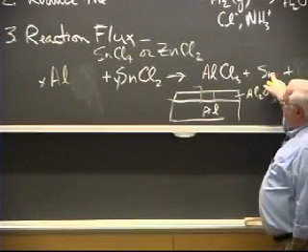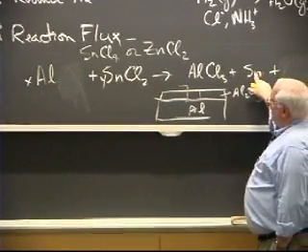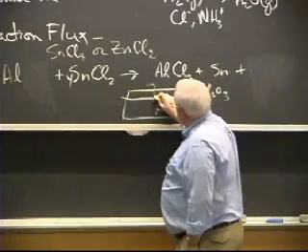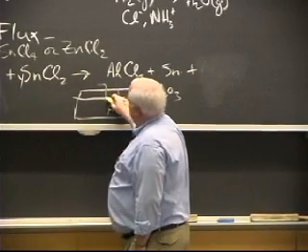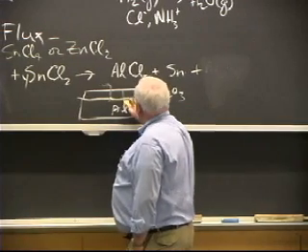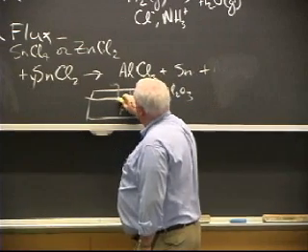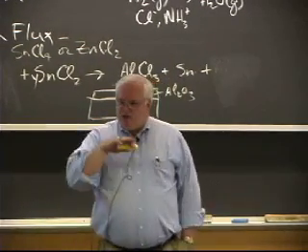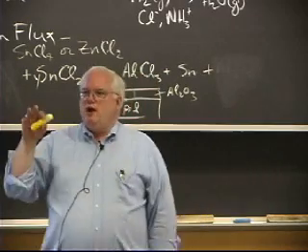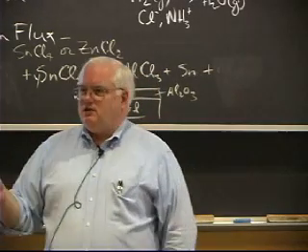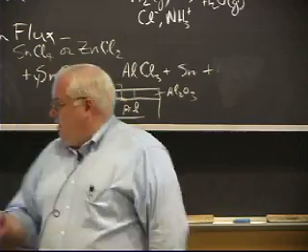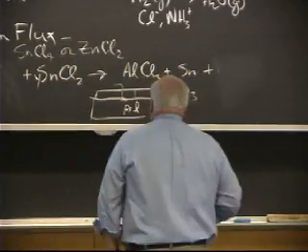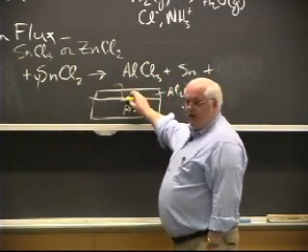And so there is a reaction here. Down here is where the aluminum metal reacts with the tin chloride and forms aluminum chloride, and the tin precipitates out, and you basically get a molten layer of tin that floats away the aluminum oxide. The aluminum oxide doesn't actually get reacted with or dissolved. There is a chemical reaction, but it is with the metallic aluminum.